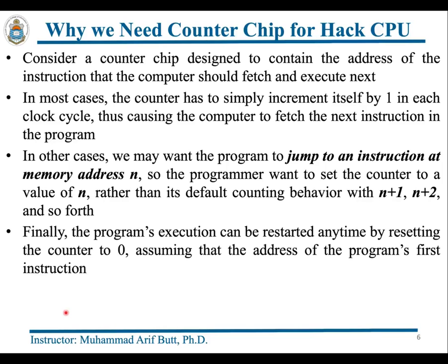Finally, the program's execution can be restarted anytime by resetting the counter to 0, assuming that the address of the program's first instruction is 0. So if I sum up this slide, what we need is a loadable and resettable counter. By loadable, I mean a counter that can be loaded with a specific value. By resettable, I mean it is resettable to a specific value which is normally 0, and it has an incremented behavior by default.